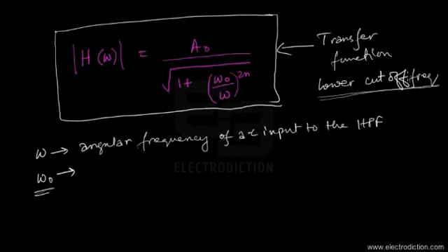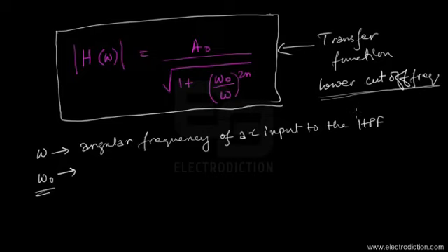So this cutoff frequency actually demarcates those electrical signals that the filter is taking at the input. It demarcates which of the frequency signals would be passed to the output by the filter and which would be attenuated. It just demarcates the boundary between the signals that are to be passed, having the frequency above the cutoff frequency, and those that are to be attenuated that lie below the cutoff frequency. So that's basically what the high pass filter does.